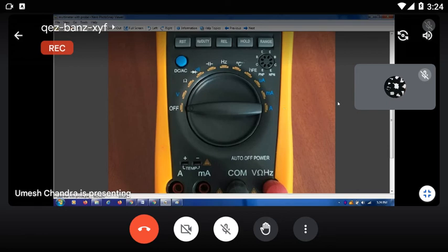Sir, please show in this picture how to join the probes. So you said we have to join the probes so that it works. Oh, okay, so just the Wi-Fi symbol. When you check continuity, you select the diode mode, and here there is a blue switch, you press that.